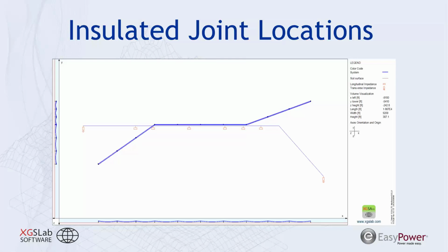When you're really incorporating this type of mitigation, you may have additional concerns during the faulted state, because during that faulted state you can have significant induction again for a short period of time, but that is a significant induction and significant voltage that can break the dielectric strength of this insulated joint intended to protect you from AC interference, and it's really causing a new issue to resolve.